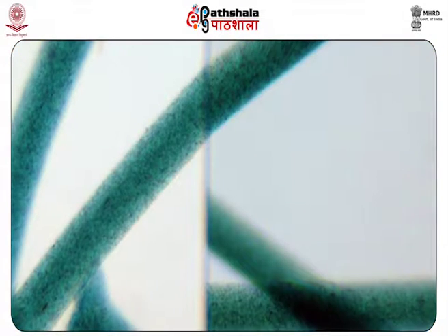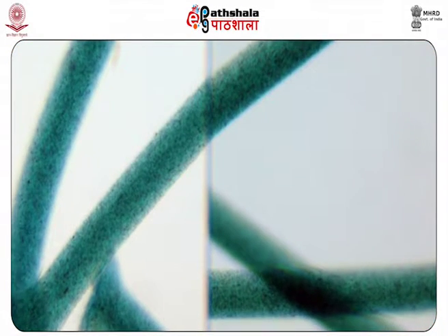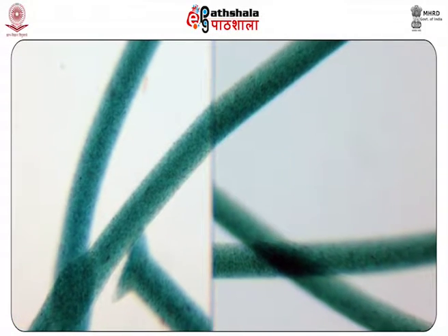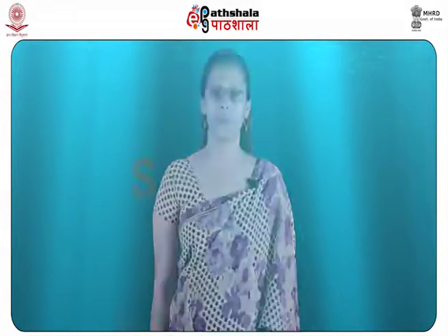However, one must know what the fibers look like under a microscope, as many finishing processes like mercerizing and delustering change the appearance of the fibers under the microscope. Apart from it, dark colored fabrics also cannot be tested with a microscope, as light cannot pass through dark substance. For those fabrics, either the cloth dyes have to be removed by stripping, bleaching, etc., or they have to be chemically tested.